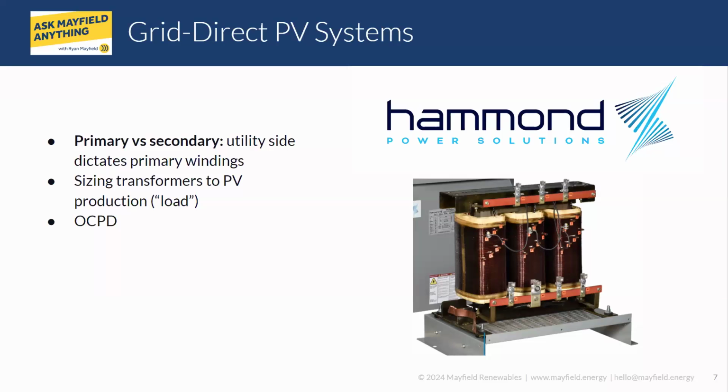There are actually several things that are different about the transformer to help it manage those high harmonic environments. It doesn't do anything to reduce harmonics. The transformer is designed to perform under its labeled load, even when harmonics are present in the system, because harmonics create more loading on the transformer than it would see in a system without harmonics.